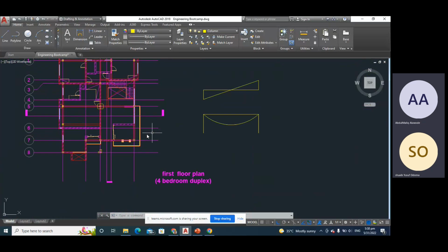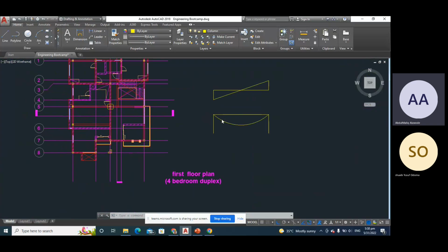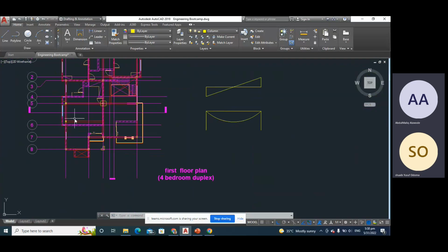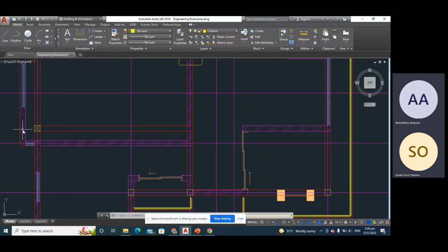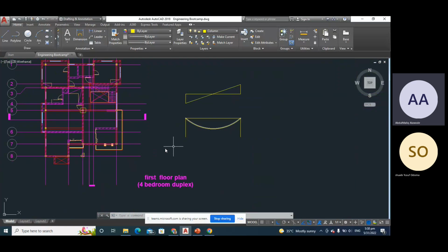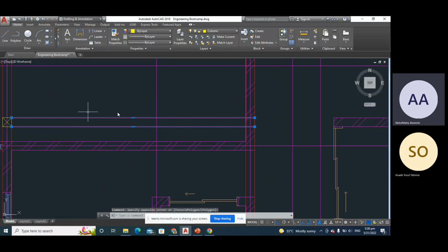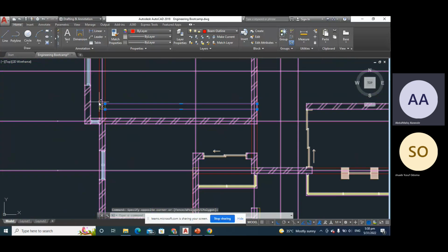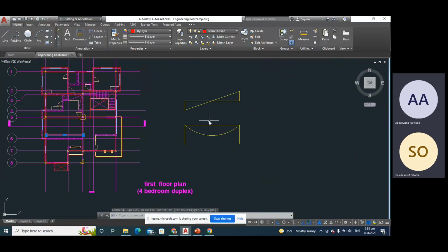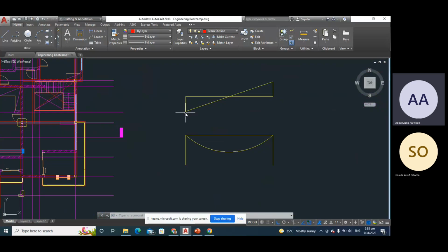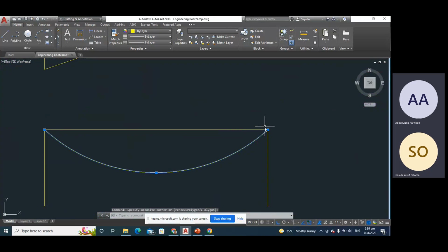Okay, that's fine. So now, if you observe this beam, since we have taken it to be pin, what pin support means is that the only thing I want this beam to do to this column is to transfer force alone. Don't take any moment. That is why at this point and at this point, we have our moment diagram to be 0.